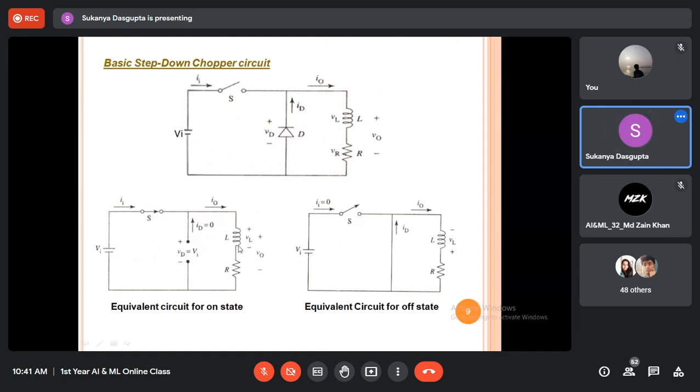So whenever there is a rate of change of this I, the voltage will be developed across the inductor. And since it's a DC circuit, when the input current will reach its steady state, that means the constant value of current, say for example I ampere, there will be no change of current present in the circuit. So voltage developed across the inductor will be 0. But till then, there is a rate of change of current during this transient period, and voltage will be developed across this load. So there will be some voltage V naught. So this is case 1, when the switch is closed.